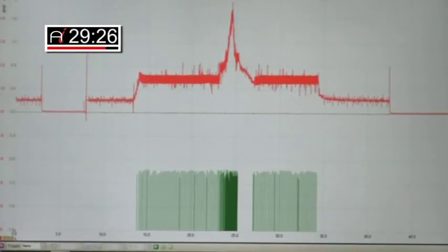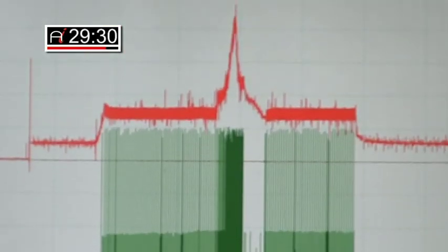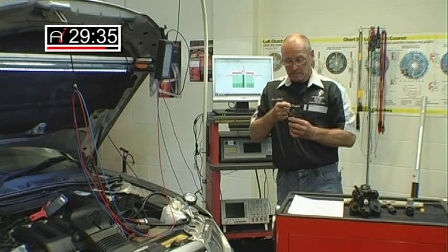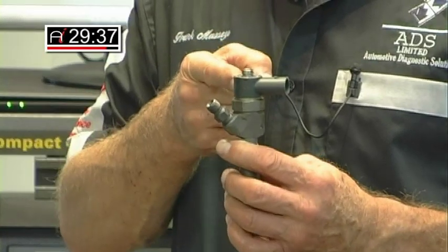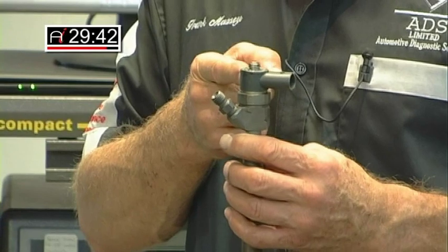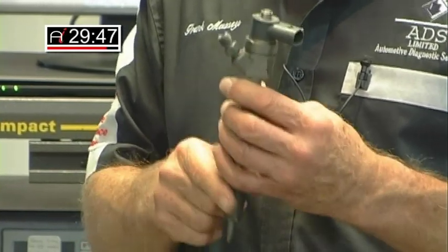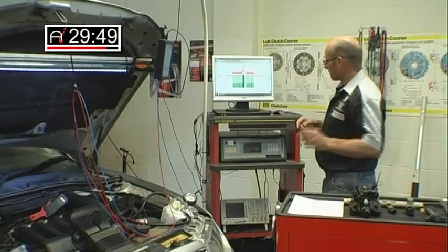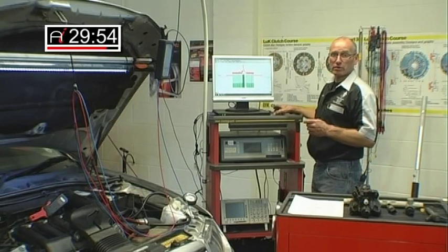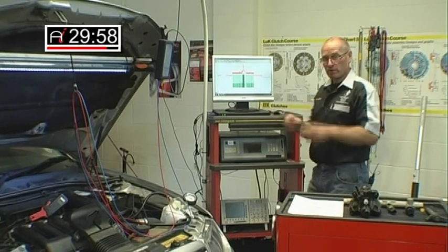However, we haven't looked at the injectors. That was a separate DTC, which potentially could be the cause. If you recall, what I said was, if an injector coil were to fail, or the ECU capacitor were to fail, then it will not drive the injectors, the vehicle will cut out and or not start. The capacitor voltage referred to is the voltage that you will read through a scan tool, 60 to 80 volts, ideally nearer the 80 volt mark. Remember the rule?